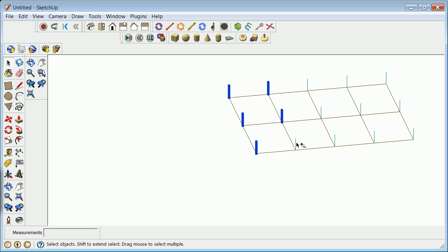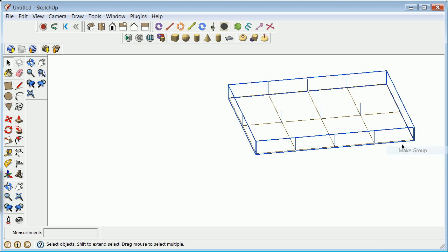You'll see this of course is not unsimilar to what you do in Revit. The difference in Revit will be that as you change the grid or change the level, these things will move along with them. So they're tied from one thing to the other. So in other words, the girder will be tied to the column. If the column moves, then the girder will stretch. And of course the column is tied to the grid. I'm going to right click, make that a group.